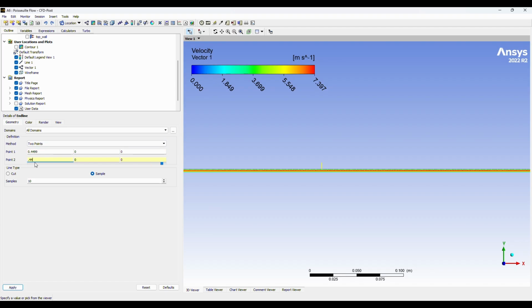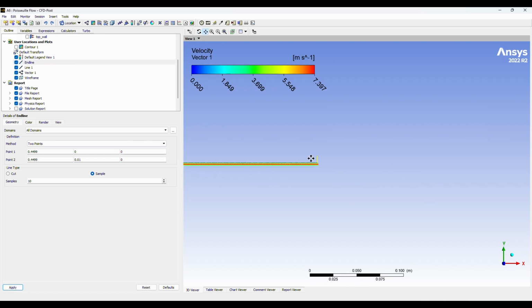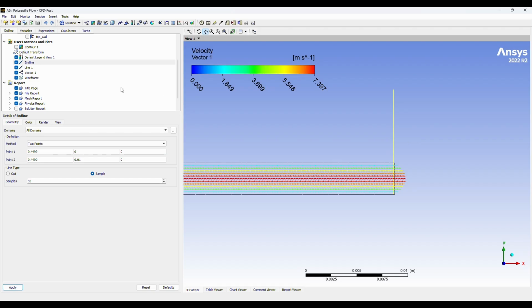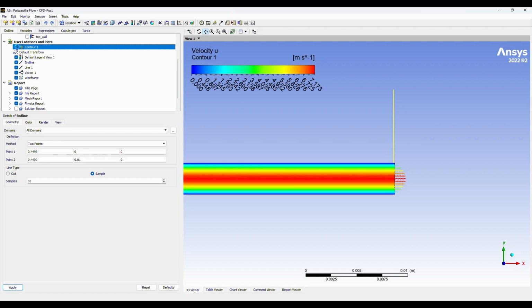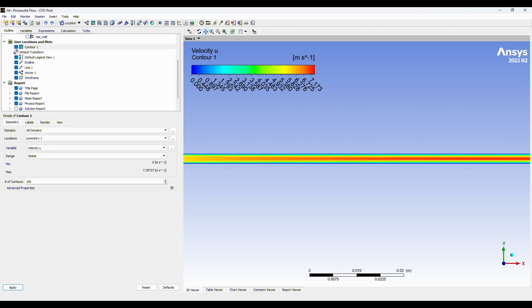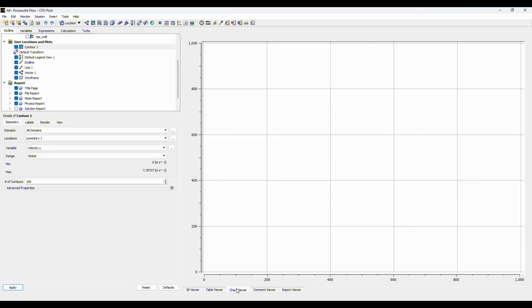Or I wouldn't say that, I'd say like 1/5 of the way to the midline is where the developing flow kind of stops. So we can see the velocity vectors of our inline, which looks good, what we expect, and this is the developing flow.